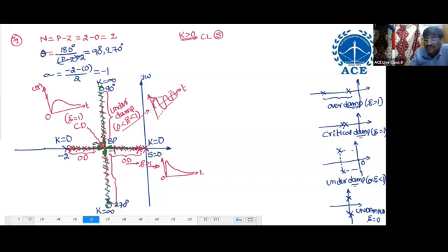So this particular system has overdamped nature, critical damped nature, underdamped nature. But it does not have the undamped nature. Undamped means poles should come on the imaginary axis, two poles like this. Then we can say it is an undamped system. But here no poles are coming on the imaginary axis. That means this system has overdamped, critical damped and underdamped nature.